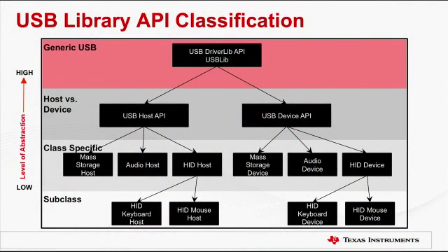There are about 125 APIs in the USB library, and for further clarification, they can be classified into 4 key categories or levels. Each category indicates the level of abstraction that API provides to the end user. At the top layer of the USB library, there are application interfaces that provide easy access to the various types of peripherals that are supported by the USB library. Below this layer are the USB host controller device interfaces that handle the specifics of each type of device and how to communicate with the USB host class driver.